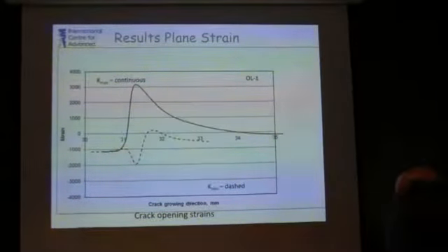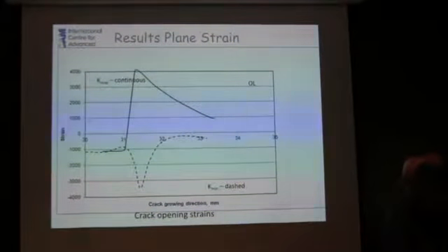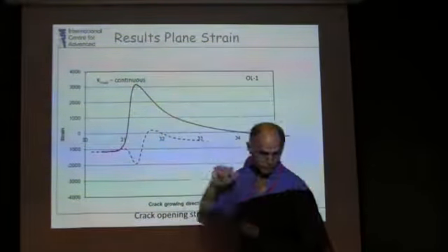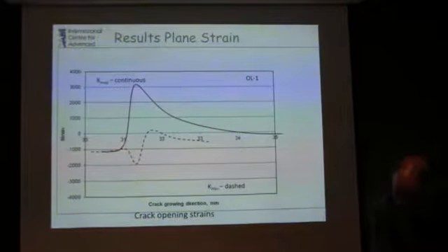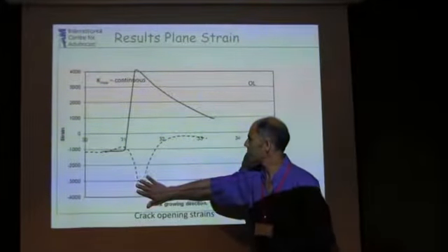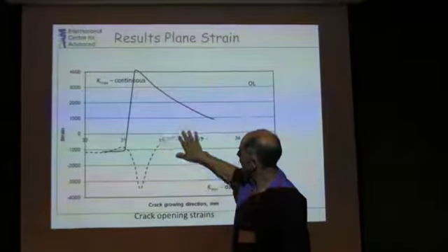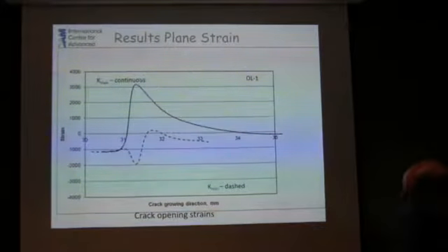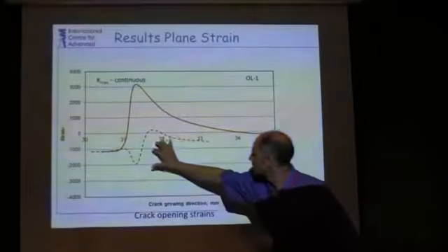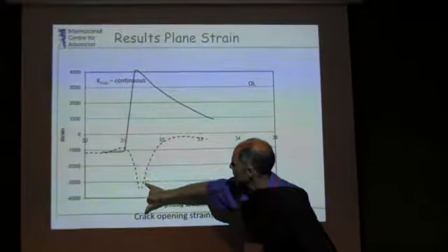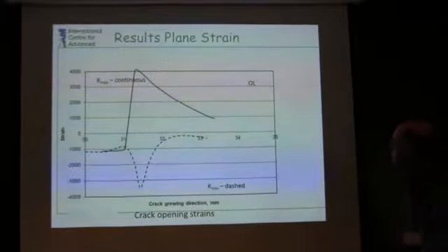So that was Kmax. That's twice Kmax, so that's overload. Not surprisingly, it's not twice the strain. The strain goes from 3,000 microstrain, so that's 0.3%, to 0.4%. We get a much larger compressive zone when we unload, as one might expect, so that the compressive region is larger and deeper. It's gone from maybe, let's say, 1,000, if you just take the difference there, to something nearer to 1 to 2,500, so it's at least double.